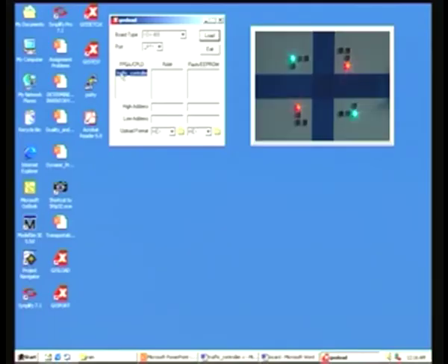The traffic controller bit stream is loaded by using GXS load here, and we have already seen this in the manual, covered earlier. This is the board type XSV 800 selected here, and the connection is LPT1 parallel port, and that is what is put here.